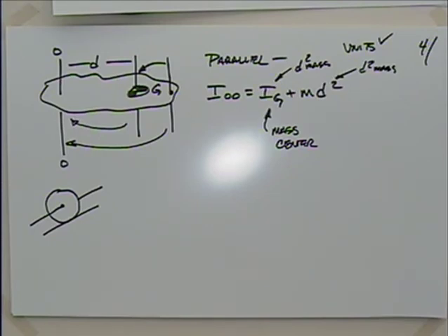Yeah, I mean, it helps to hook the transmission to the engine. Probably the biggest thing is if we look at the engine, most engines are 4-stroke, and we'll talk tomorrow about 2-stroke engines. But let's say 4-stroke engines. Most of you came to school today in something that was propelled with a 4-stroke engine. So if I have a single-cylinder 4-stroke engine, it's producing power what percent of the time? 25% of the time, right?